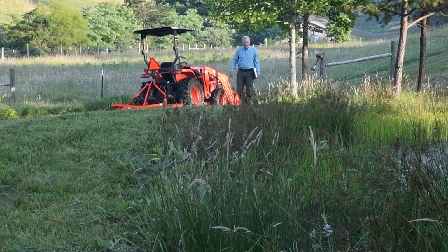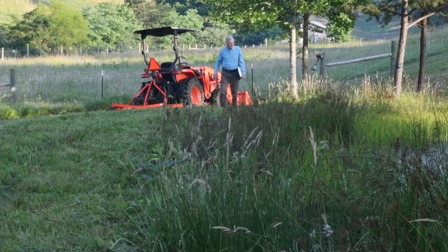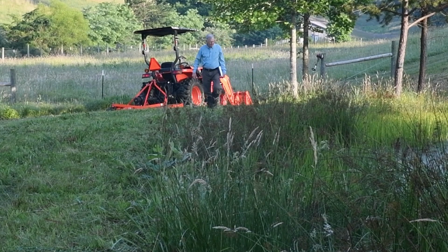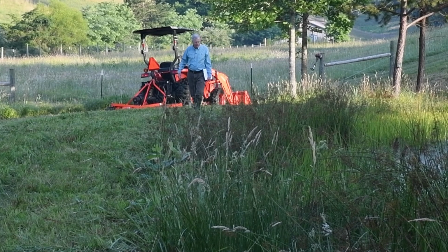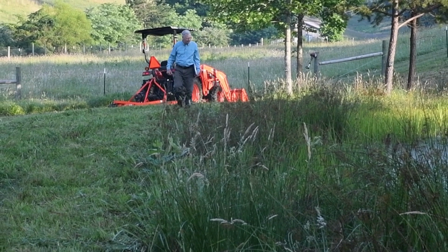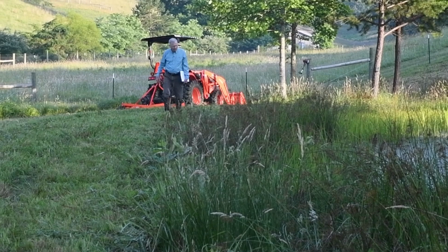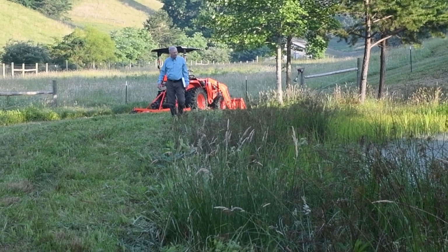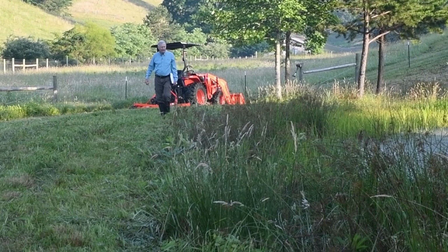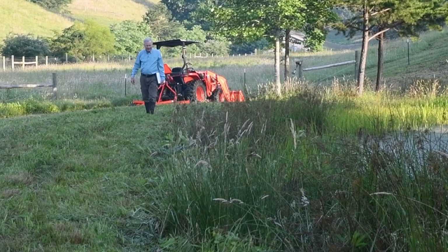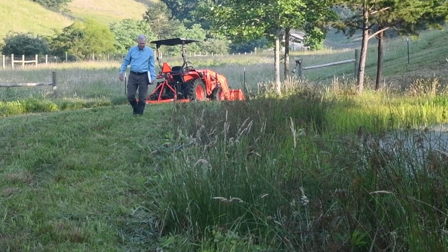I'm going to start by walking the peak of the dam, or the crest of the dam, and going slowly and looking for any burrows that have been made by muskrats or canals that have been made by beaver. I don't see any holes, but I see a great diversity of plants that are growing along the inside slope of the dam. And again, it looks like the water level's to capacity.